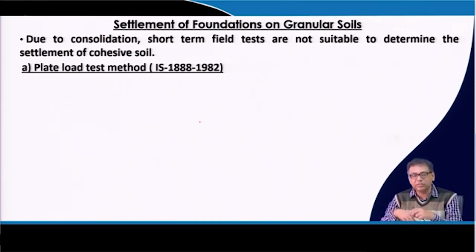So, that is why it is not recommended to use these test data directly for cohesive soil. You can use them, but you have to cross-check with other methods also in the case of cohesive soil.